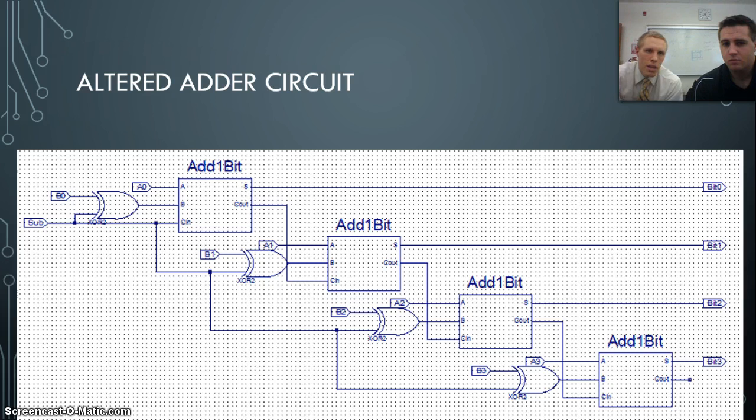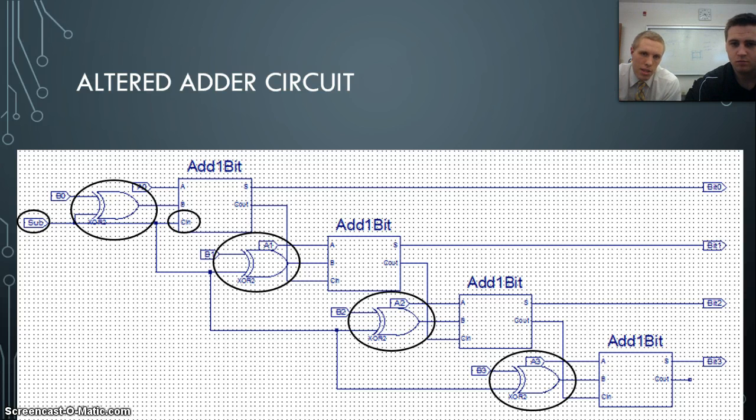And we've tried to organize the ALU mux diagram so that it's native and makes sense and follows that pattern. And then this is quickly our altered adder circuit. We essentially put in some exclusive ORs to be able to handle subtraction, and this is seen here as those exclusive ORs. And those handle the B inputs, and that's where it's triggered. So the second word that gets sent in is B; A would be stored in register 0 and B would be stored in register 1, and that determines where we want them. So if you want to deal with signed numbers, put them in the second register.